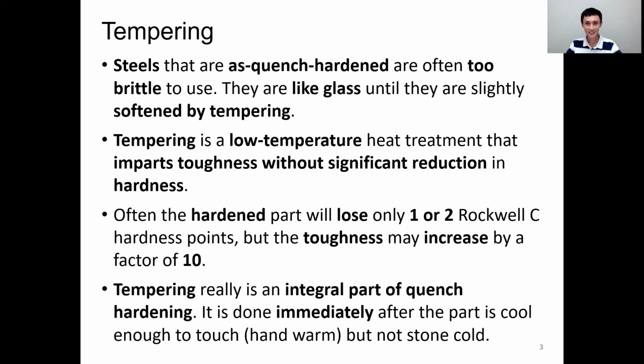However, martensite is not always good. The pros of martensite are that it has higher strength and higher hardness. On the other hand, martensite is usually too brittle to use, and it is like glass until it is treated by a process called tempering.